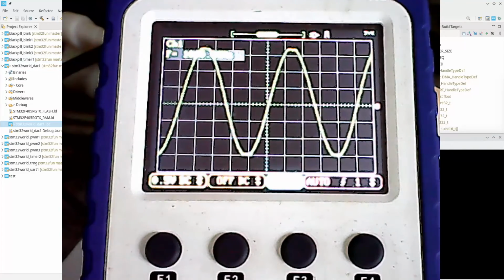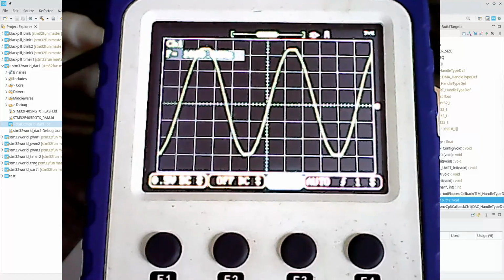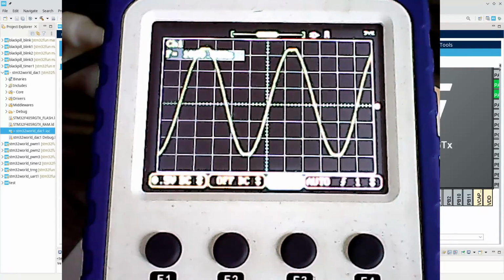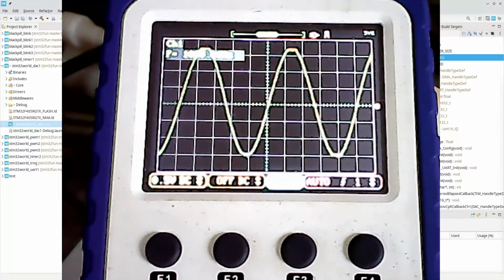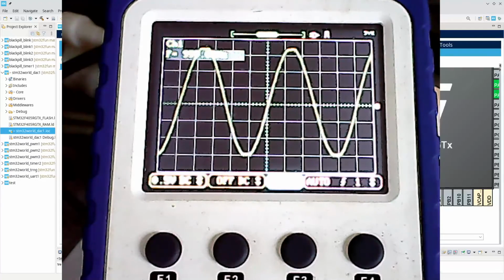We could actually probably up this to 200. I'm saying that, let me try it. So let's try to see if we could actually run it at 200 kilohertz. I honestly have not tried this, but I suspect that it could actually work. So let's change the timer to 5. 5 minus 1. That's only 4. Let's see. Generate code.